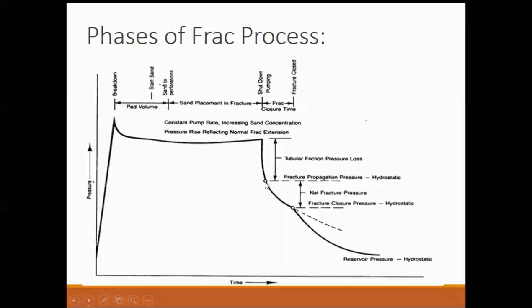So when you let the fluid leak off further in the formation, the pressure will drop down further and it will indicate a slope change. So this point you can mark as a closure pressure. At this point you can say that your fracture is closed.